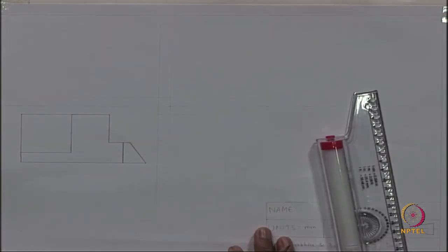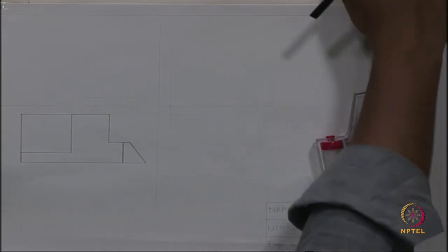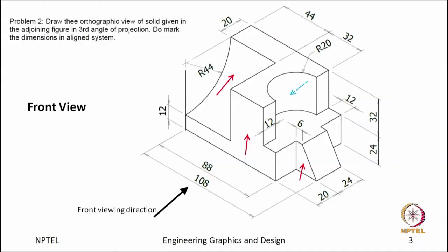We are done with the front view? We are not. I showed you that you have a hidden feature here. The hidden feature, what is this? Again a half cylindrical cavity. And what I said, what you will see in the half cylindrical cavity? There will be a generator of the cylinder. This generator you will see as a hidden line if you look from the front. This generator and the lower cavity part as a horizontal line. These two lines we will be seeing as a hidden feature.